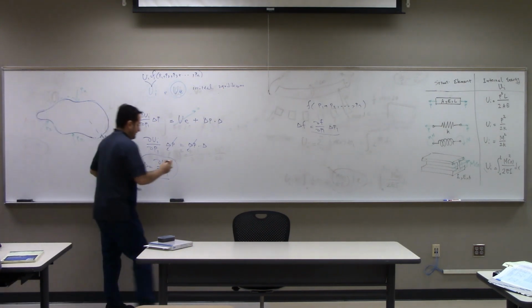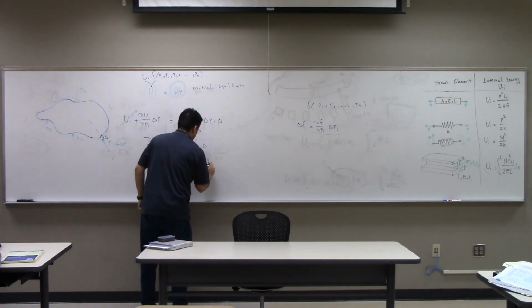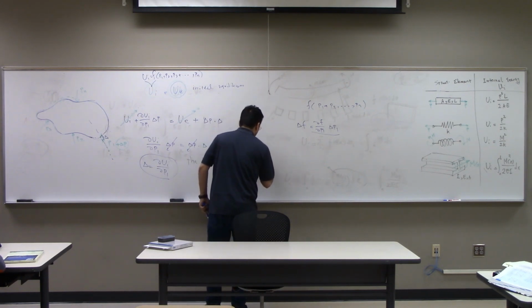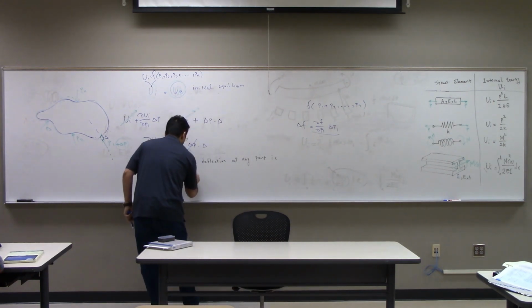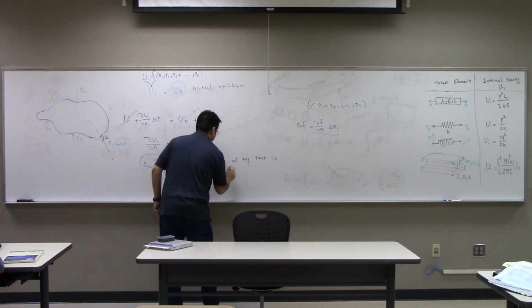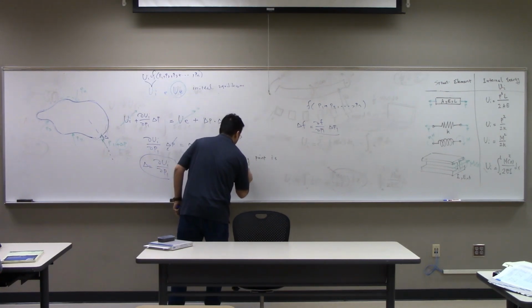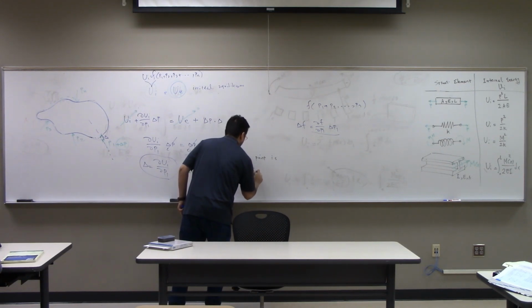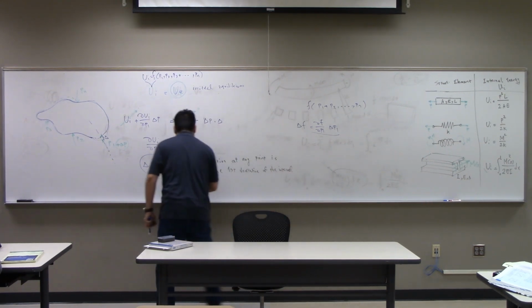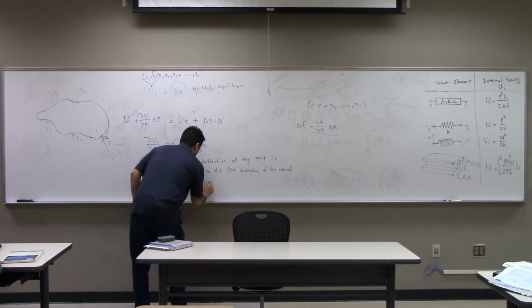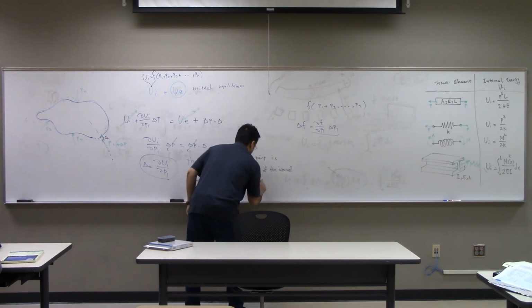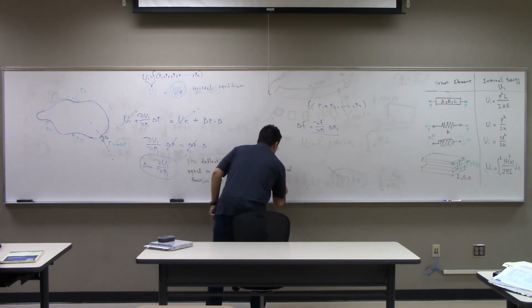The deflection at any point is equal to the derivative, or the first derivative, of the internal function with respect to load P1 applied to that particular point.